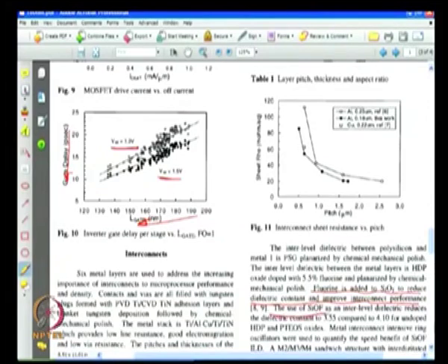The use of SiOF as an interlevel dielectric reduces the dielectric constant to 3.55 compared to 4.1 for undoped silicon oxide. Remember, for silicon oxide the dielectric constant is around 4.1, whereas that comes down to 3.55.